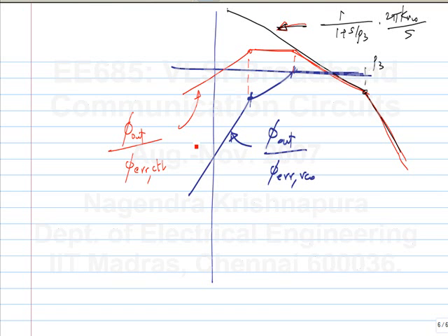So roughly speaking, it is low pass from the input to the output. So if you have a noisy oscillator and you want to clean up its noise, you should use a low bandwidth PLL. Okay. The PLL is used in two ways. It can be used with an accurate, very low noise crystal reference to generate a variable frequency, in which case you use an oscillator, and any oscillator you make is likely to be much more noisy than the crystal oscillator.